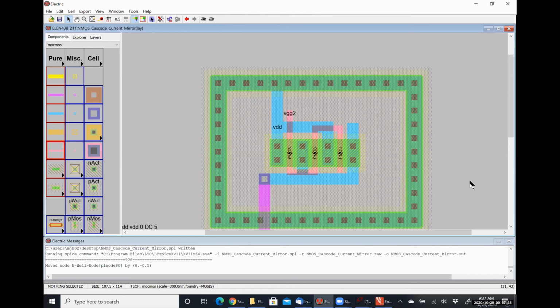Because it does, exactly what you said, it does make the parasitic capacitance seem like it'll be smaller because we don't have as much area of overlap between the metal 1 layer and the polysilicon 1 layer. So seems like a reasonable change. And probably the last question that I have today. Okay.